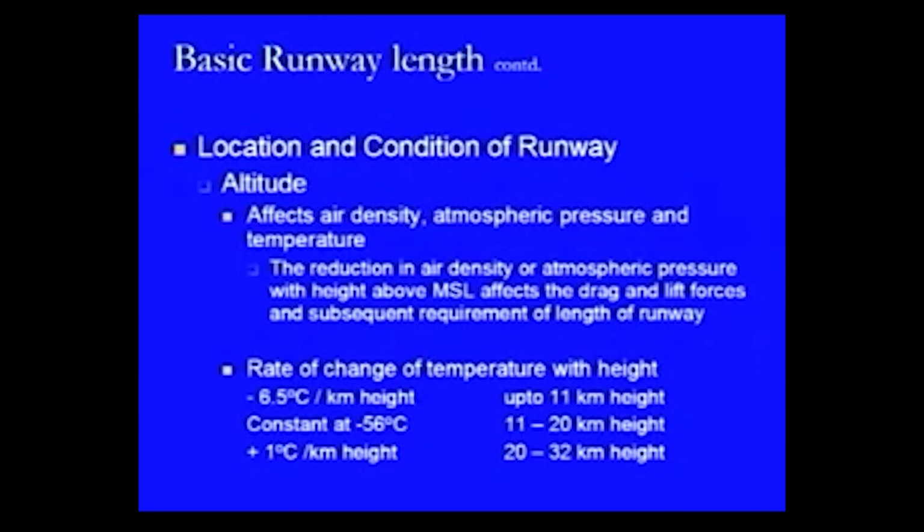If there is a reduction in air density or atmospheric pressure with height above the mean sea level, then it affects the drag and lift forces, and therefore longer runways are required at that location. And the rate of change of temperature with height, because these two things are correlated with each other, is 6.5 degrees centigrade per kilometer up to a height of 11 kilometers from the mean sea level.